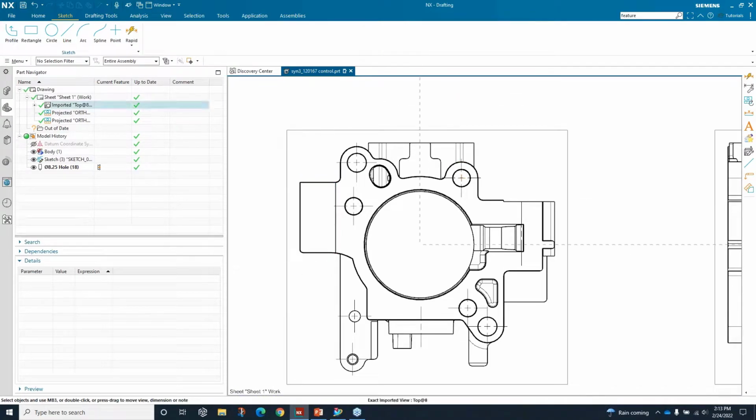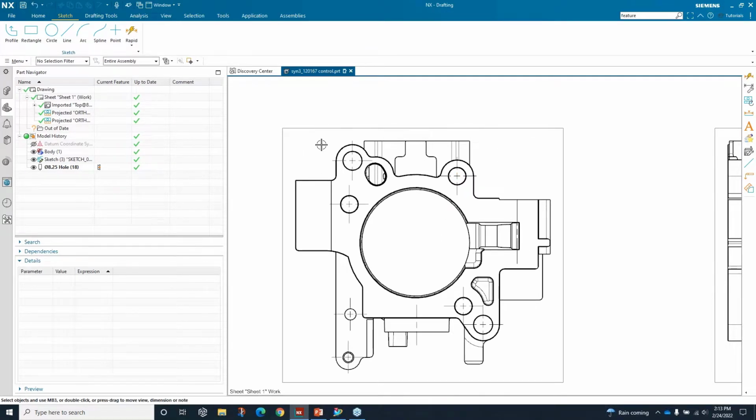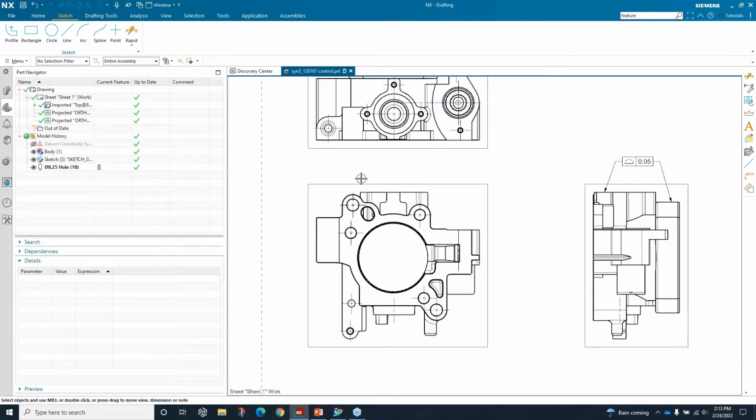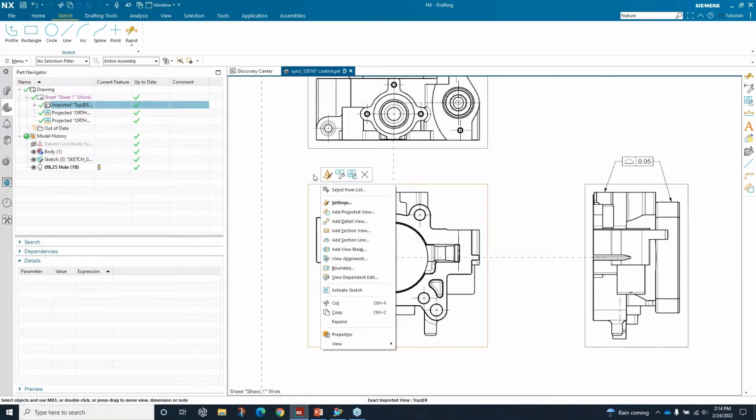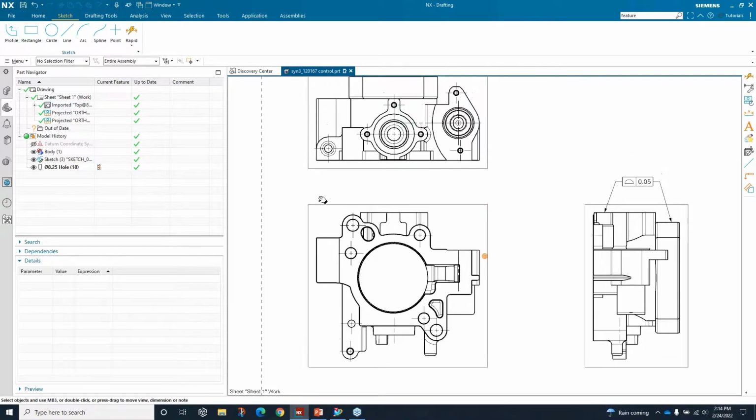And finish. Okay, now the test. Hey, it moves right with it. So you could see it's not that it's difficult to do, it's actually pretty easy. It's just that we are frequently missing the step of right clicking and then active sketch view.